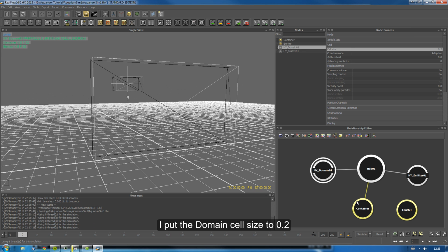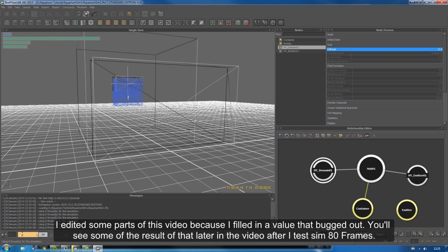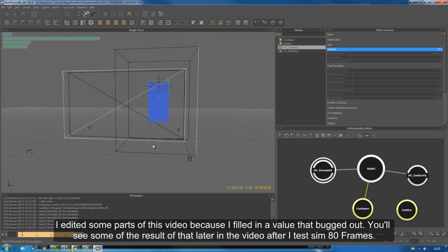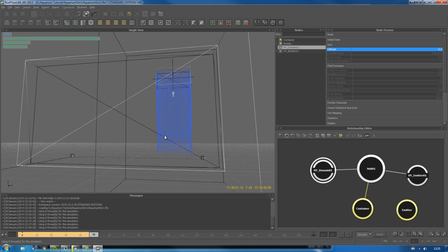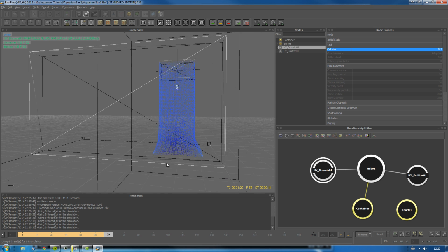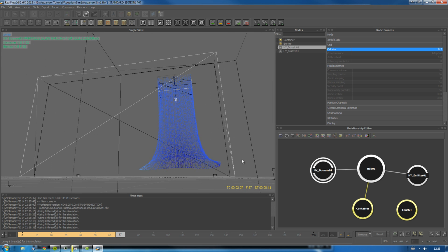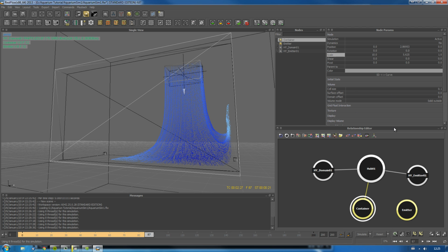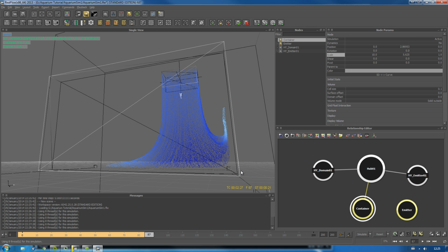Okay, sorry for the jump. Let's try it with this resolution. Here we go, there it comes. Ah yes, here you see it's slowing down way too fast, way too early. We can fix this. In a container, you have a surface offset. At the moment, the surface for the particles is over here, rounded off. Let's move it over to the actual edge of the mesh.